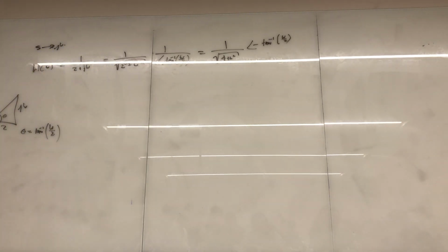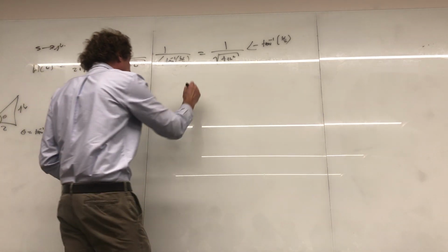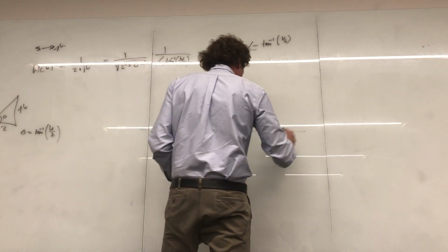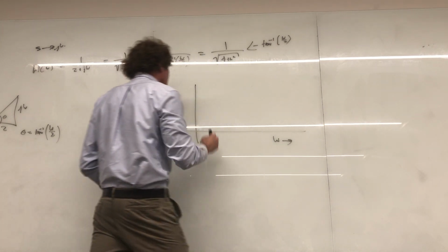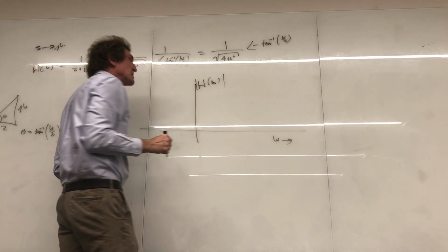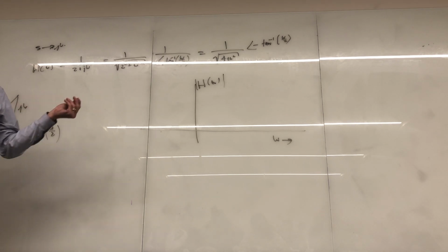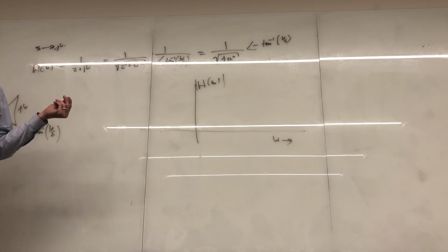I asked you to plot both magnitude and angle, right? You're going to see this is very easy to do, but you have to be attentive here. When I plot the magnitude of anything, I want to show you the trick on this one. This is going to be the magnitude of H(omega). The first place you start is at 0. You evaluate the function when omega is 0, or any function. You want to evaluate the origin.